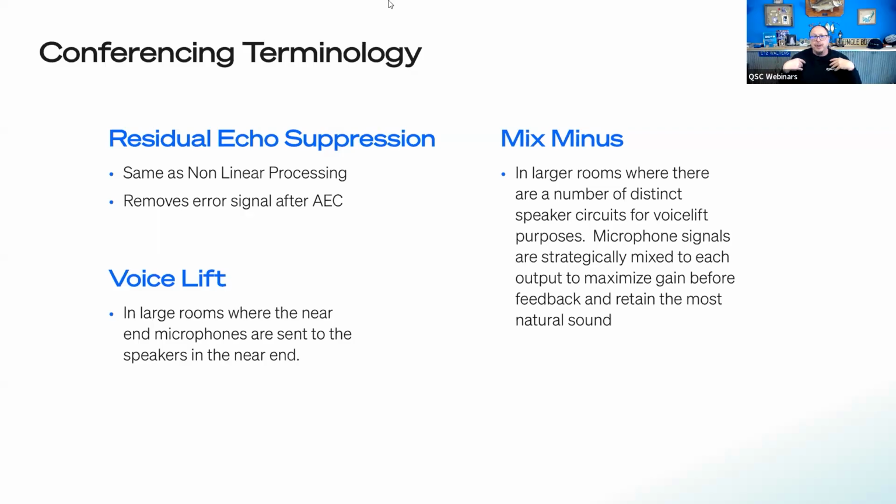For voice lift, I'll give the example of a training room where the instructor is 99% of the time at the front of the room and may have a lavalier mic on. With voice lift, I'm going to go to the back row of loudspeakers, maybe 30 feet away. My voice really only carries a good 15 feet. So 15, 20 feet back in the room, I may have a row of loudspeakers that lift just enough of my voice, not so that it sounds like Sunday, Sunday at the monster truck rally. It should just feel natural. And, you know, sometimes you have to argue with your customers.